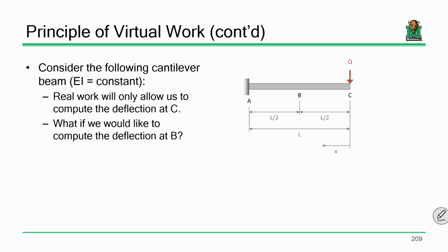What we do with virtual work is a little strange, but the long and short of it is it makes sense when you think about it. For virtual work, what we do is we say this. Anytime we write an energy principle, it only works for where we apply the load. So we say, all right, is that how it's going to be? Then we'll just apply another load. We'll apply a load where we want to determine deflections.